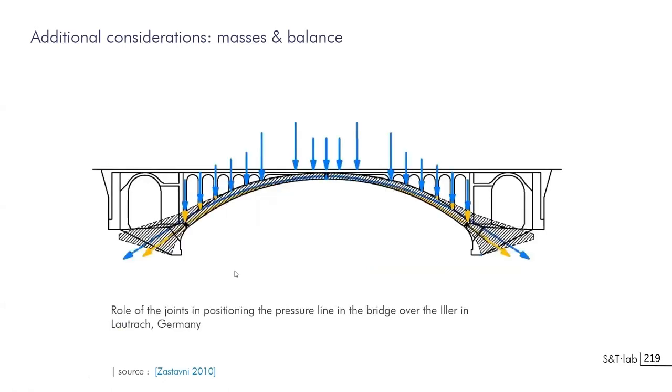If you are drawing an arch that has a certain thickness, you can have a thrust line that is running anywhere into the system and you cannot decide. But as soon as you develop a specific device that will be hinges in the arch, one central hinge and two side hinges, you have to draw the thrust line passing through these hinges, and this will decide where the line of action will have to pass on both sides and in the middle.